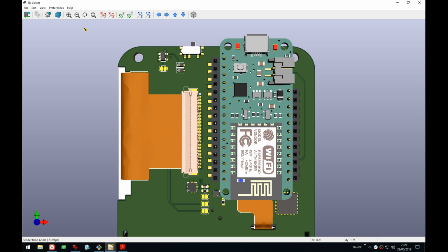the last thing, in a short version, is you want to know the dropout voltage, which is how do I explain this? It's the difference between the in and out. So if you had 4 volts in, but you need 3.3 out, and the dropout voltage is 2, then that just wouldn't work, because the most you can get from 4 with a drop of 2 is 2. So you have to make sure that it will physically allow you to drop the voltage from your input to output. And that's kind of it.